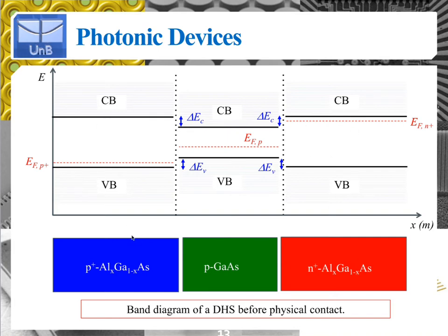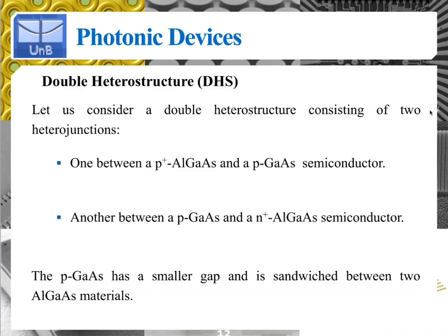So it's different because it's n-type, but it's also heavily doped, and this means that the Fermi level, since it's n-type material, is up towards the conduction band. And because it's heavily doped, this means that the Fermi level is very close to the band edge for the conduction band. So again, the gallium arsenide, which is lightly doped, has a smaller band gap, as we've seen,